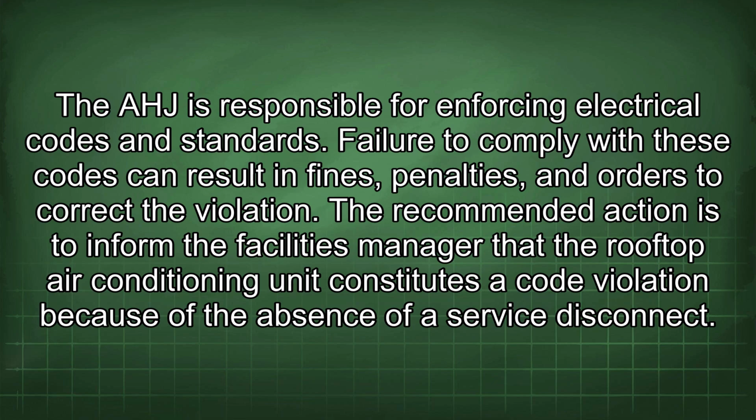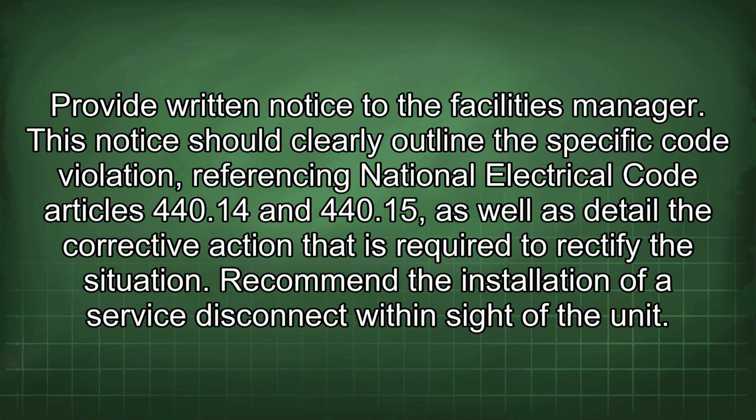The recommended action is to inform the facilities manager that the rooftop air conditioning unit constitutes a code violation because of the absence of a service disconnect. Provide written notice to the facilities manager. This notice should clearly outline the specific code violation, referencing National Electrical Code Articles 440.14 and 440.15, as well as detail the corrective action that is required to rectify the situation.